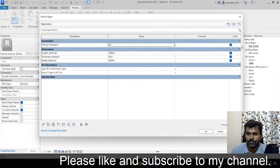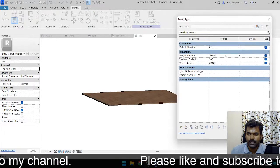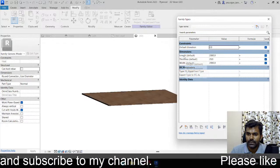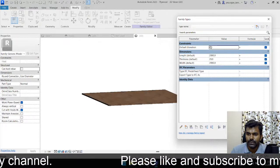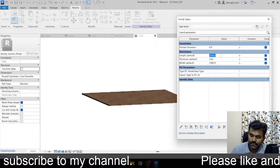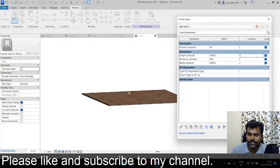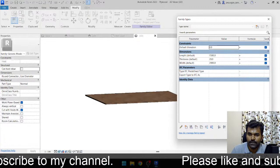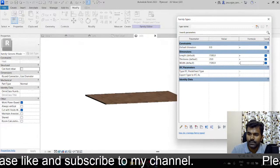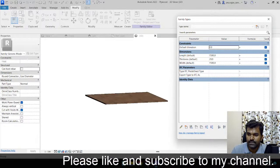We have to check our parameters, so that's very important. This is my family types window. This elevation is supposed to be 0. That's how we don't mess up the offset. Now let's try to change this length. If I press apply, I watch here, it should change. Apply, this is changing. Width 1500. If I apply, that's changing, but only from the right side.